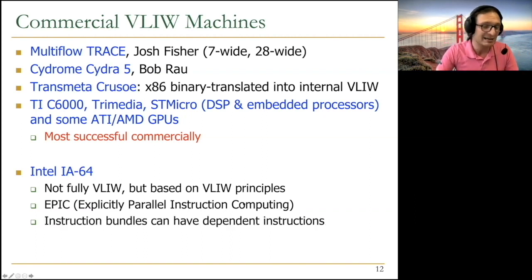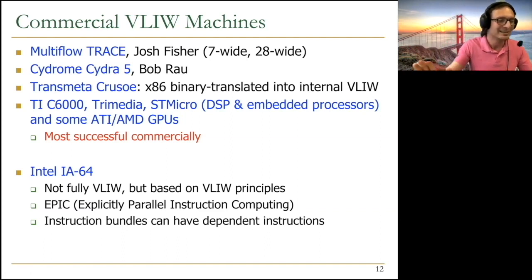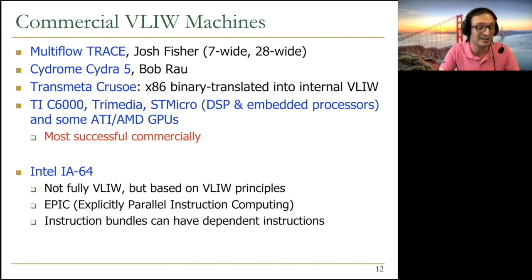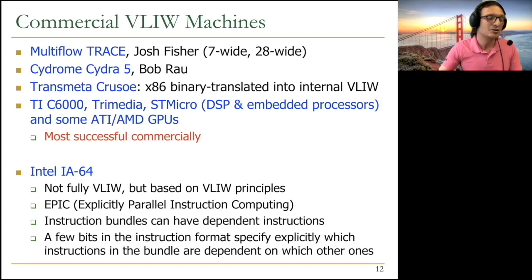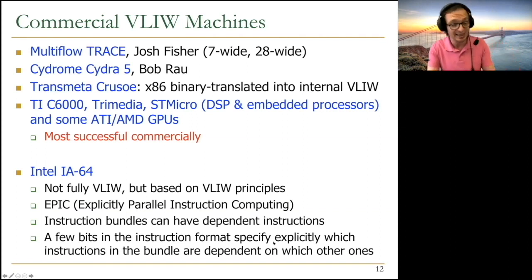And the basic idea, there are multiple differences, of course, from VLIW, but what they introduced was instruction bundles can have dependent instructions now. So if you think about a pure VLIW perspective, it's a big no-no, right? I cannot have dependent instructions in my bundle. Because if you put dependent instructions in your bundle, now hardware needs to check. Now, to make hardware's job easier, they changed the instruction format such that a few bits in the instruction format specify explicitly which instructions in the bundle are dependent on which other ones. So this is actually a cool thing. Basically, they encode the dependencies between instructions explicitly so that the hardware's job is a little bit easier.